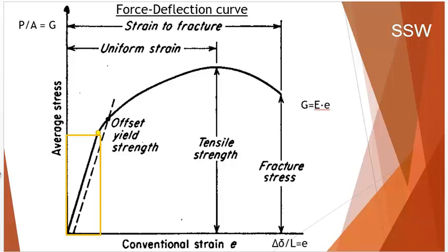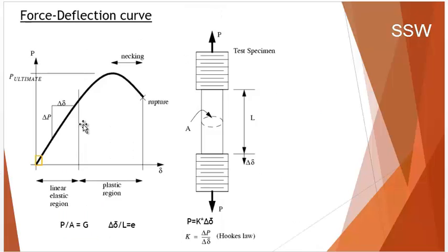So why do we do that? Firstly, because of the linear relationship between stress and strain. Secondly, because it's easier for us to solve problems. It's easier to predict the behavior of a construction, and calculations go faster. We can go further into the plastic region, but in this case solving can be difficult because of the non-linear relationship.